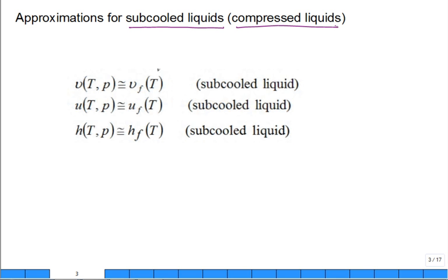So these are, what do you call, synonymous? It's just a perspective. You're just looking and saying, oh, is the pressure greater than the saturation pressure? Oh, it's compressed liquid. It's higher pressure than the saturation pressure. Or subcooled. Is the temperature less than the saturation temperature?